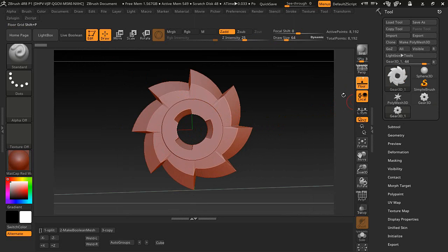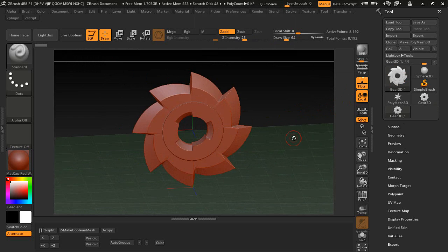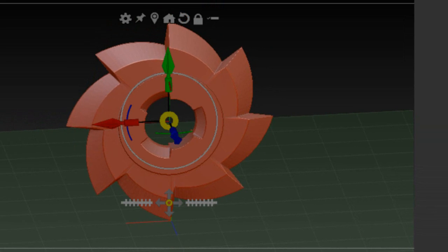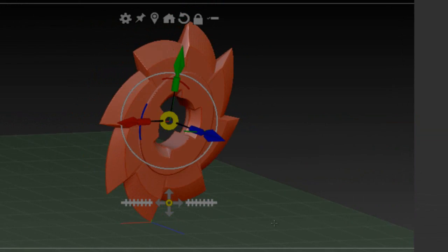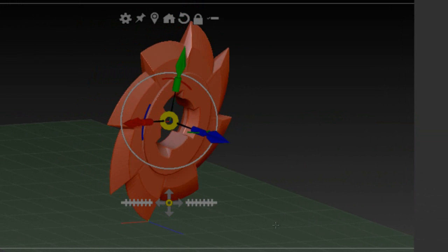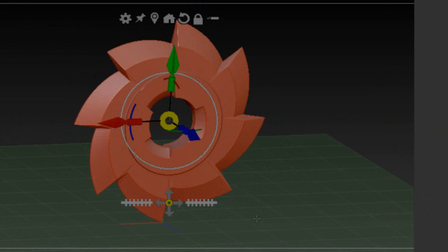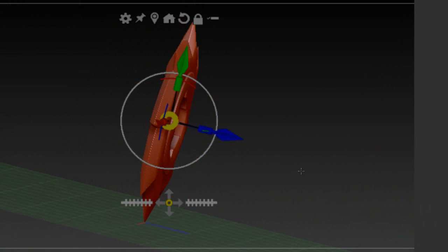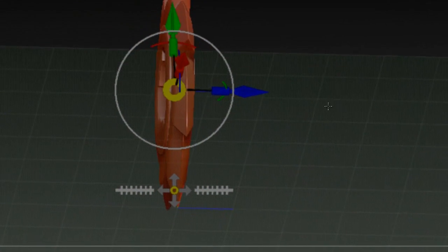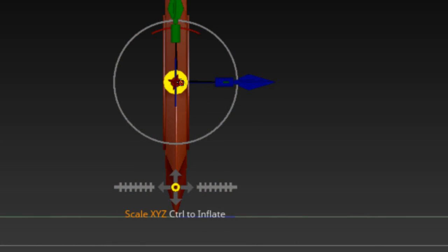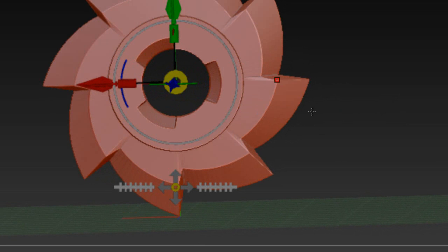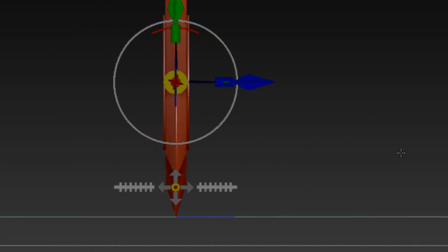We're going to turn the floor grid on, and this time we're going to have to remember 2 things. We're going to be cutting in the red axes, alright? The other thing is, when I split this, I'm always going to keep the object on the right. I'll show you what I mean here in a second. For me to cut this, I'm going to select it and hold the screen and shift click this. And as you can see, the red axis is pointing towards me and behind me, and the blues to the right. And notice I did not have to turn the gizmo to turn this around. I just turn this by the screen and snap it like that.